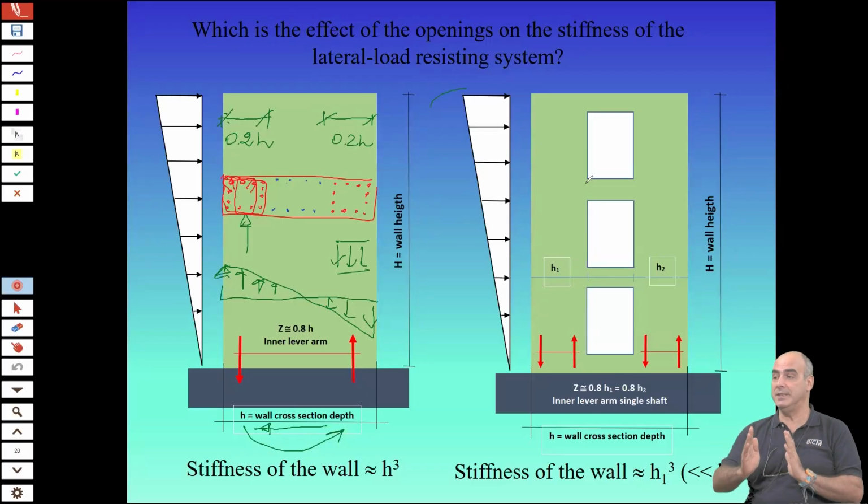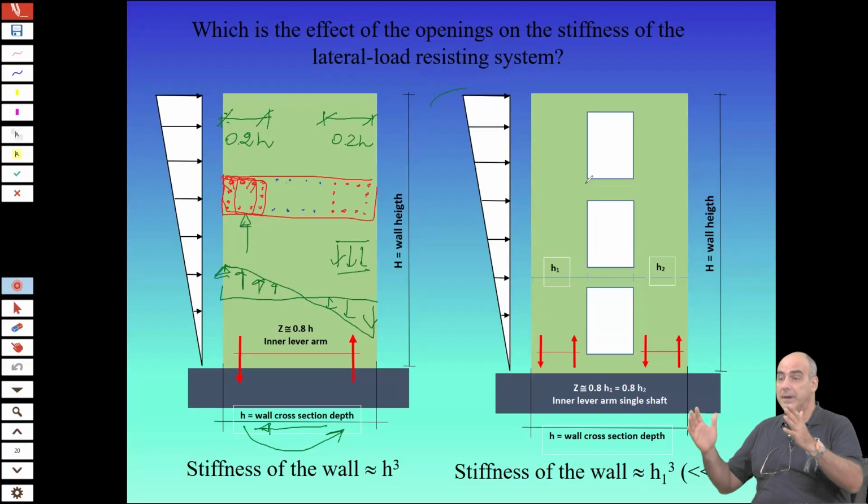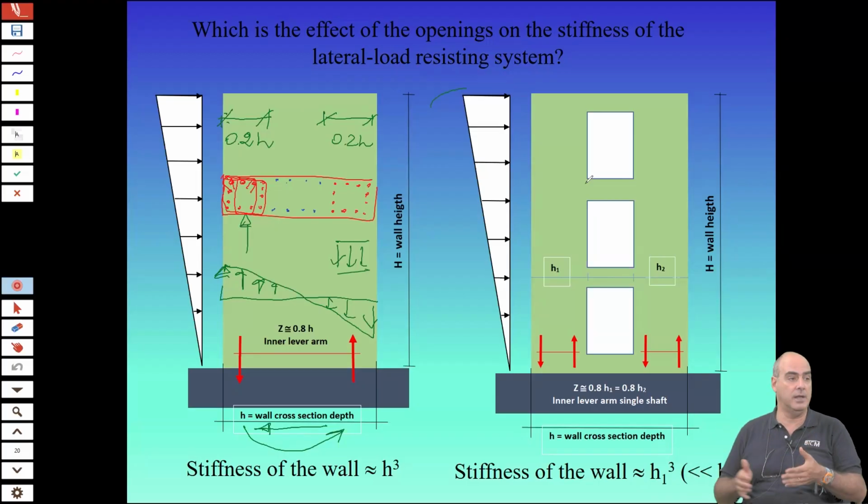1.2 meters is considered so that two people can pass. Consider that the breadth of our shoulders is 60 centimeters. Two people can pass through. So the minimum is 1.2 meters. Even more, because in hospitals you have to pass through with beds and so on. Or if you have an office, you have to consider that also.